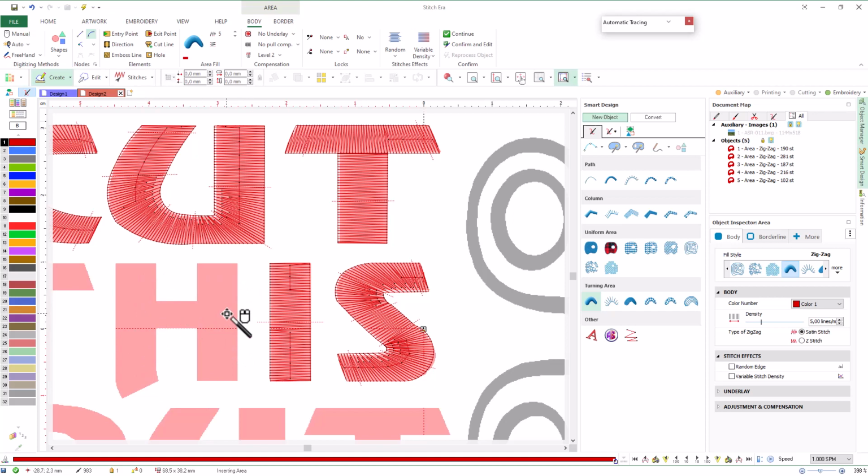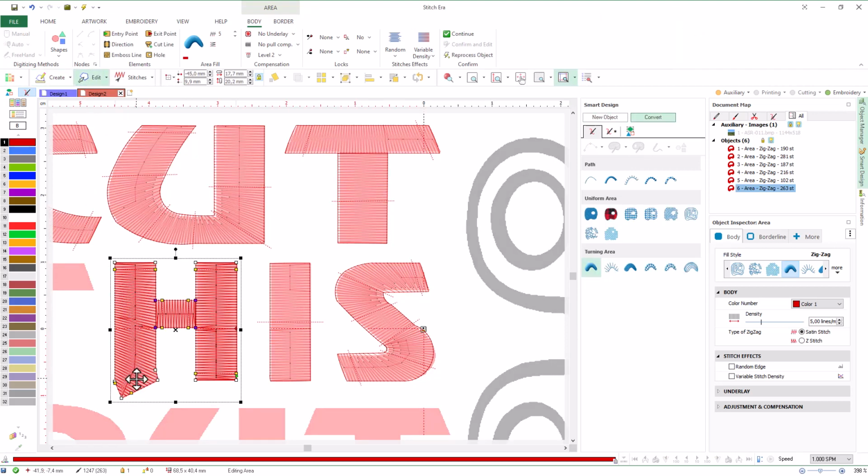However, we will use a more automated auto trace mode, called Auto Complete. Select Auto Complete and click to capture the contour. Note that the definition of geometric elements is disabled in this mode. Press Enter and the system will complete the creation of the object. Click on Edit Object to take a look at the object created with this tool. The system added cut lines to divide the contour and directions for each of the segments. To keep the style we have been using, let's edit this direction.